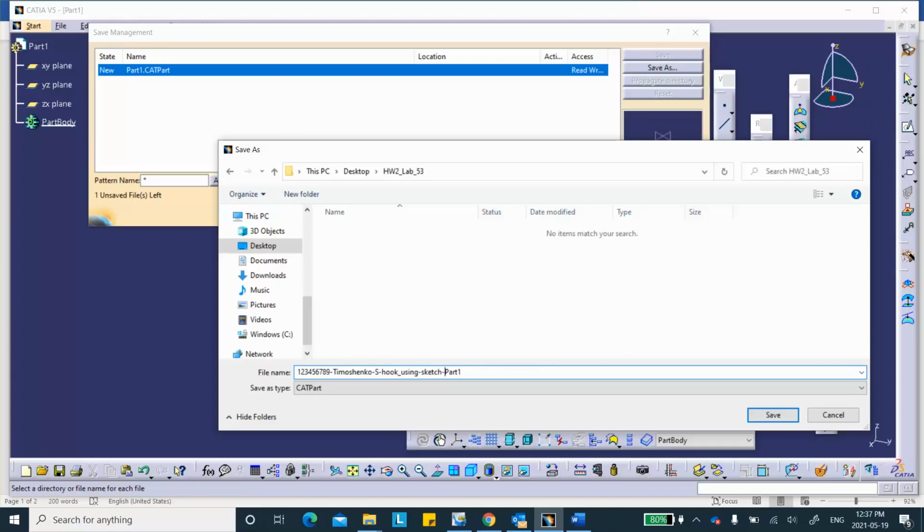Remember, you cannot just give any name that you want, and at the end try to rename it the Microsoft way. You know, in a Word file, once you save it, you can right click and rename it as whatever you want. You cannot do that with CATIA files because it will lose track. Analysis, for example, will not know that you decided to change the name of the part. You have to do this in file save management. Otherwise, you're on your own.